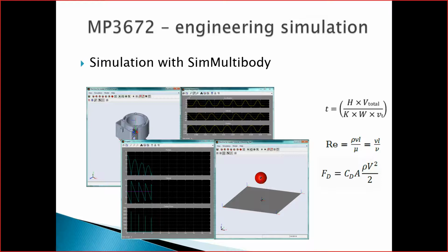The bouncing ball's fascinating. So if you consider the mesh nodes that we discussed just a minute ago, the spots, if you will, the points on the spider's web where joints will connect, that is what your resolution will be. In between the two, you'll get behaviours of materials and all sorts. If you're doing a bouncing ball, we enter a realm that they call the Hertzian problem, where if that bouncing ball hits the ground, and it's covered in nodes, what you're going to end up with is material penetration between the target, in this case the ground, and the bouncing ball.